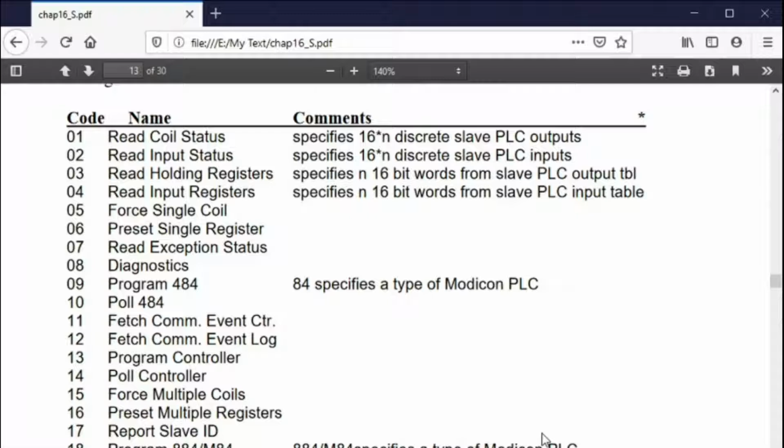But these loss-in-weight feeders we had to be able to control from an Allen Bradley programmable controller. The way that was done was through a box called Unibus. So we had Data Highway Plus, the high-speed I/O connectivity going out from the Allen Bradley, and it went to a little black box called Unibus. Out the other side of the Unibus was a control RS-232 cable, and there were three of these cables that went out to three Merrick, M-E-R-R-I-C-K, control boxes, and the Merricks were using Modbus Protocol. So they were the slaves, we were the master, but we had to be able to read and write this information.